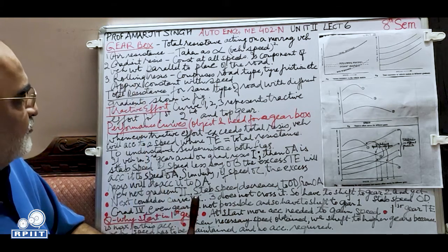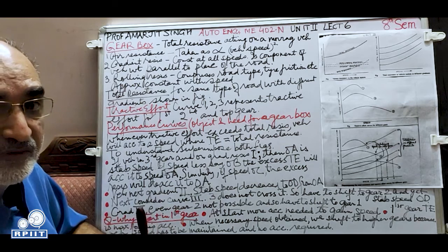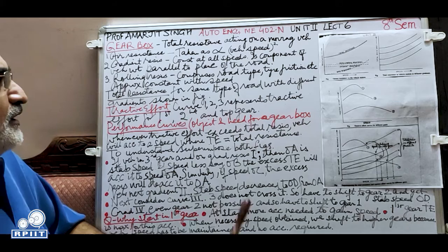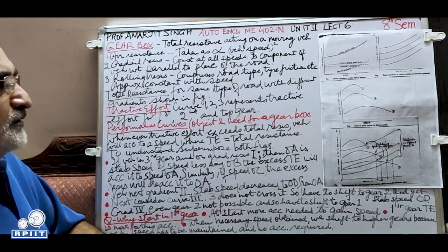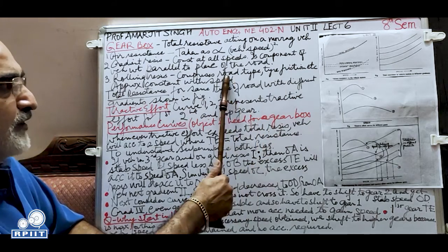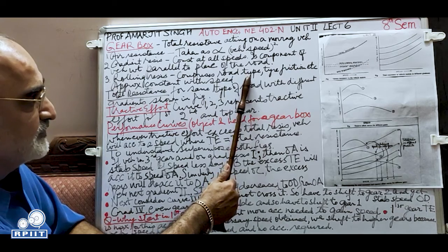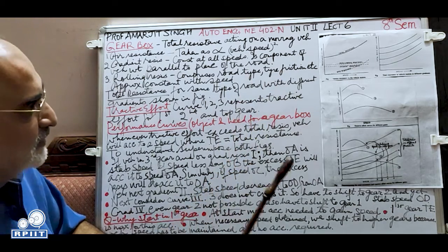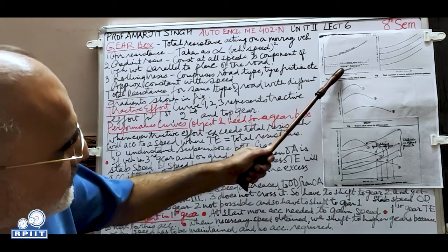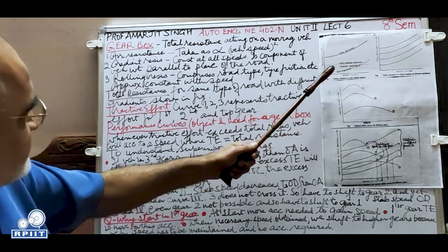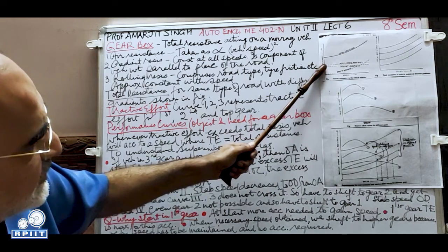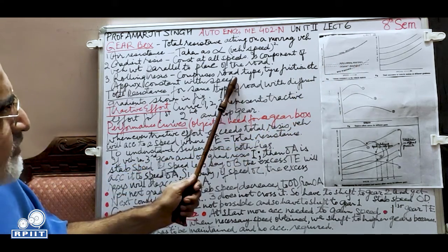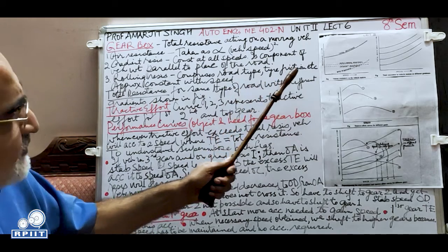The third type of resistance acting on a moving vehicle is the rolling resistance. This is due to the road type, tire friction. Different roads will have different types of friction, tire friction, and all that. So that is represented by, here it's shown as miscellaneous resistance, nothing but the rolling resistance, which is also a constant depending upon the type of road and tire friction, various factors.